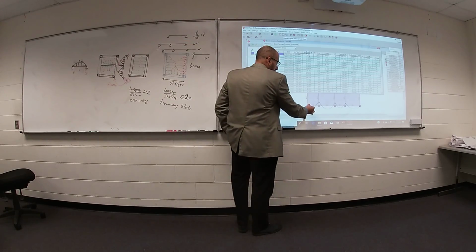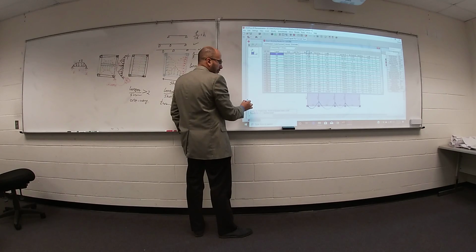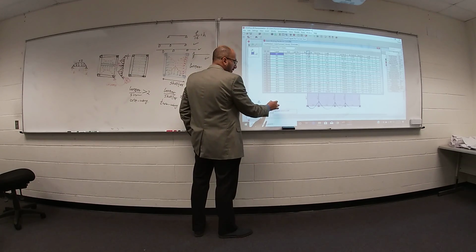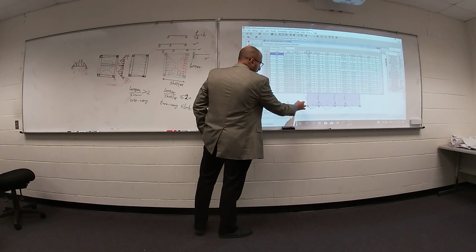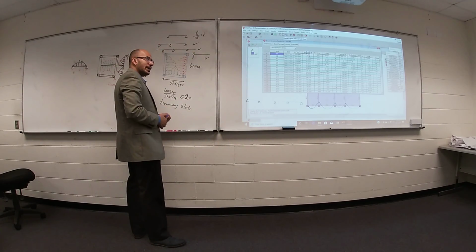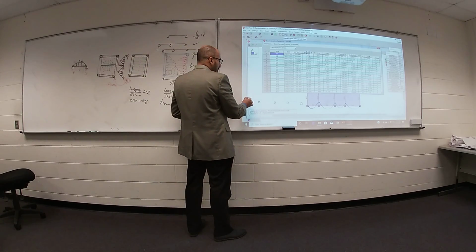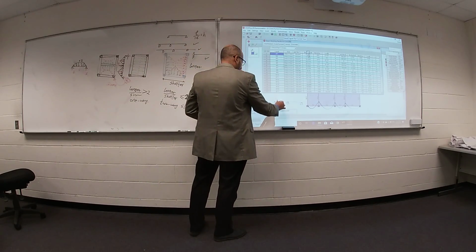This beam from here to here looks like a beam supported here, here, here, and here. We have load coming from own weight, from slab, from live load, from everything. My expected bending moment is something like this.